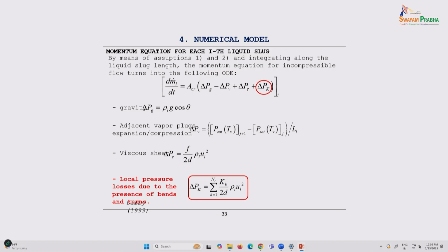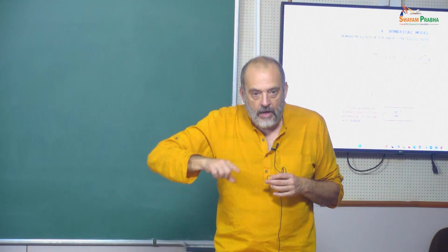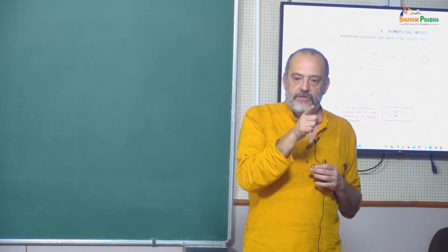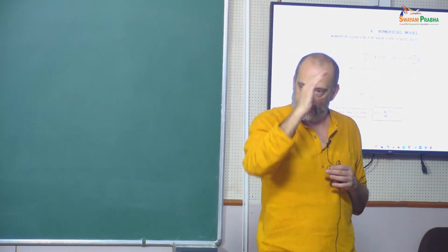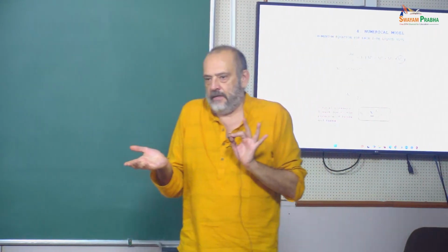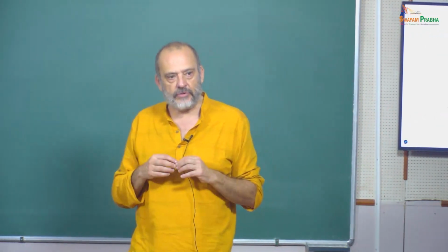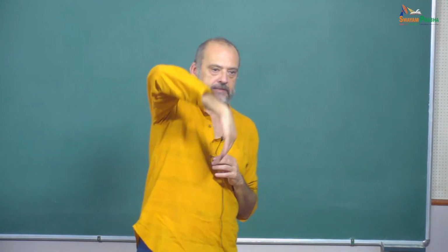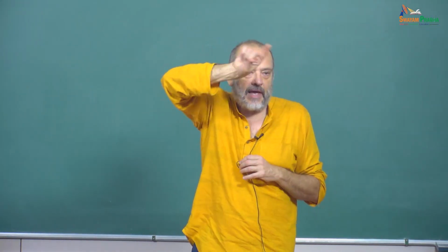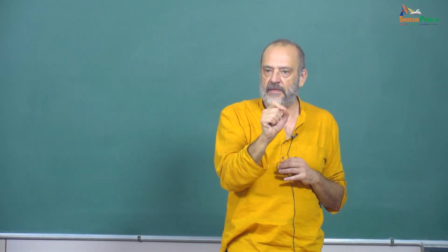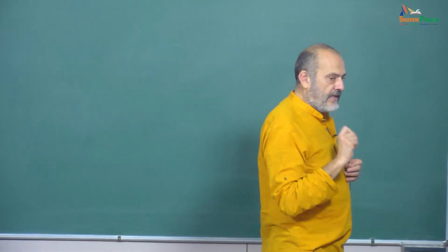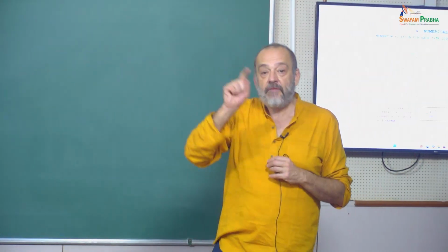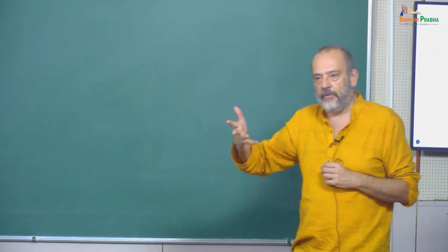So this is another point. In the pulsating pipe, what is also important is that we have turns. So we always need to add the pressure drops linked to the turns. With a very classical estimation of the pressure drops when liquid or gas passes through an elbow, for example a 90-degree elbow, you have a concentrated pressure drop instead of only a distributed one. The concentrated pressure drop is very important because we have a lot of turns, so this is not negligible.